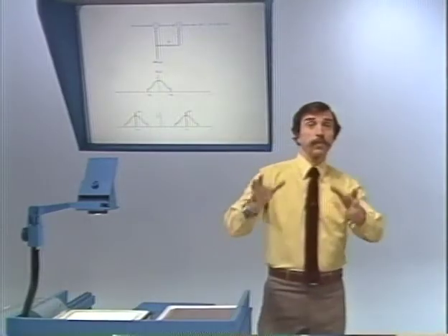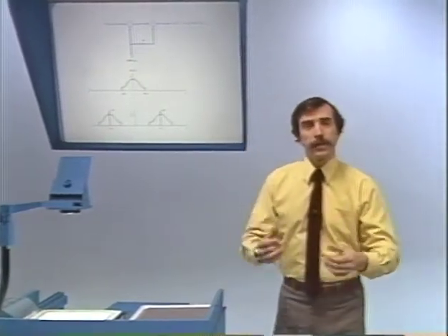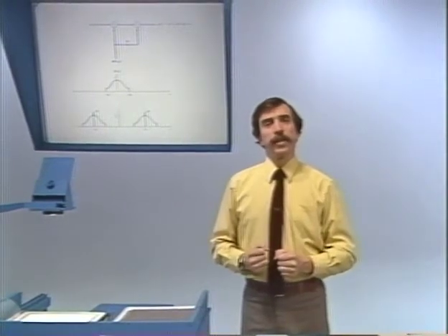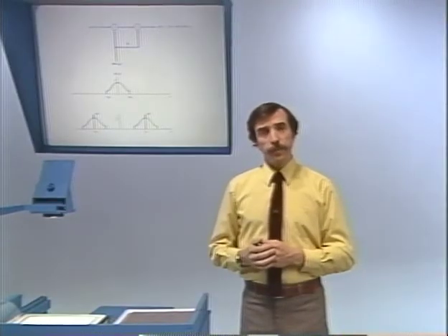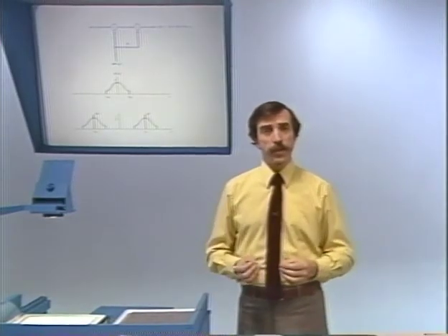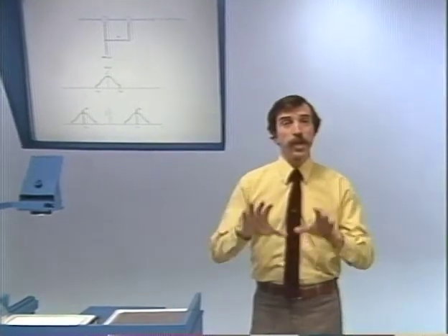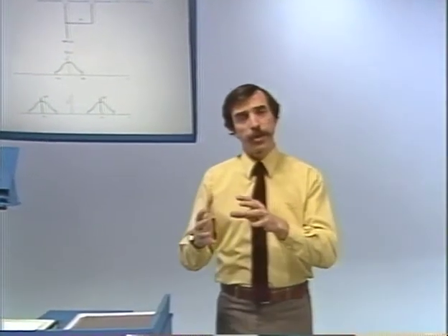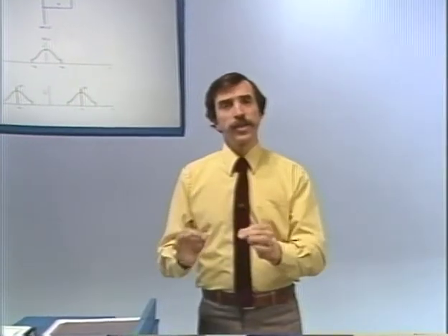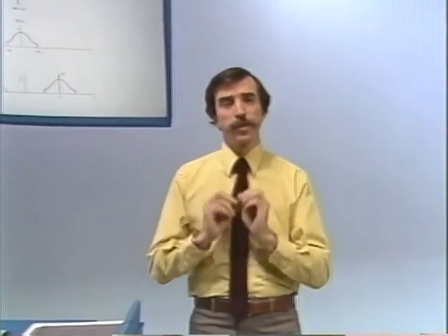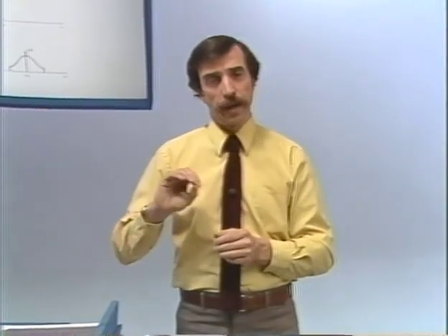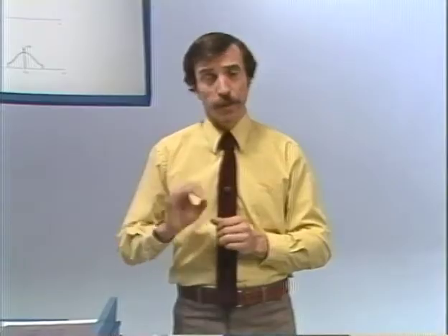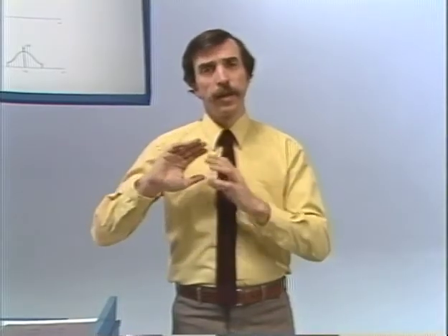So one can ask, well, why not just put a lot in? Well, the obvious answer is that it's not an information carrying part of the signal. And so in some sense, it represents an inefficiency in transmission, because what you're transmitting is power, energy, that doesn't have any information associated with it. It's simply the injection of a carrier to make the demodulation easier for an asynchronous demodulator.